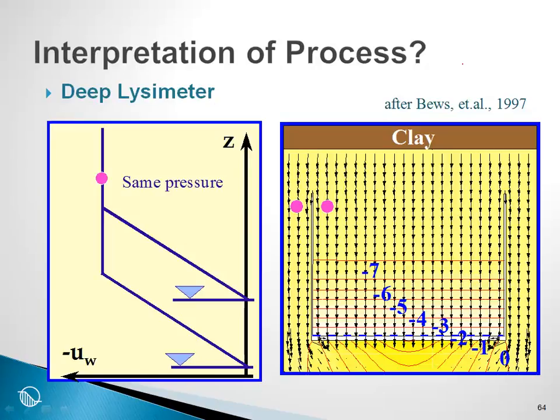Very briefly, the objective to solve this situation is that it is necessary to ensure that the pore pressure on the outside of the lysimeter is the same as the inside of the lysimeter, and when this is done, then the collection system in fact does work. I won't go into any more detail here except to note that here we once again have 100% unsaturated flow, and to model this accurately and realistically, it is mandatory to have some highly realistic conductivity functions for the two contrasting materials.